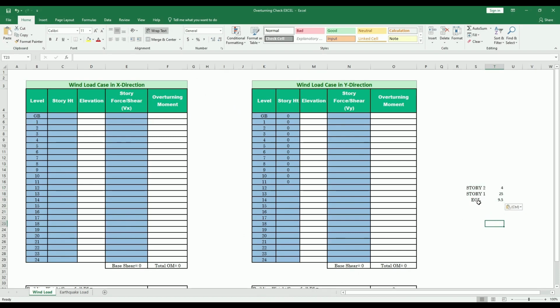But the issue is here you can see that this EGL is in the last position, but this Excel needs this value of EGL at top. So what we can do, we can take a column here by writing 1, then expand this one and then fill series. Okay, now you have to select this one from this side. Okay, now go to filter and select largest to smallest.